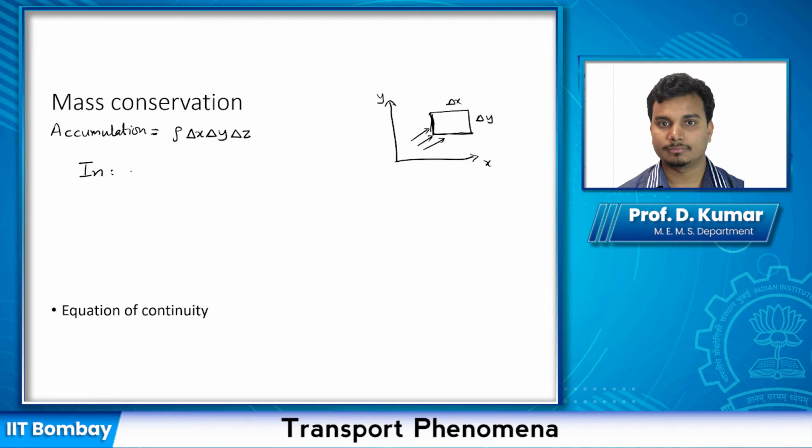So at this surface, this term will be rho times this area. So rho A V, we are trying to write. Mass flow rate is rho A V. That is what we want to write. So area is delta y, and again if I extend it to 3D, then there has to be delta z, and then you are concerned with Vx. So you take the dot product of the flow with the area vector, A dot V, and when you do, you will get Vx.